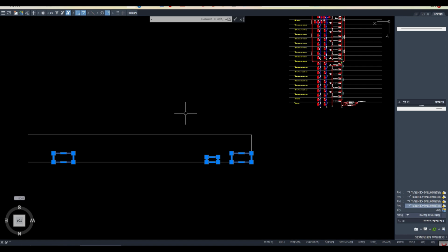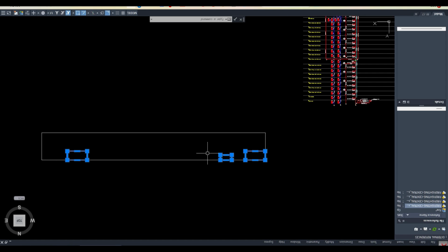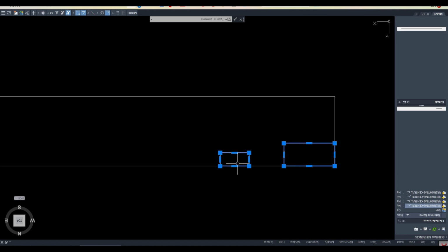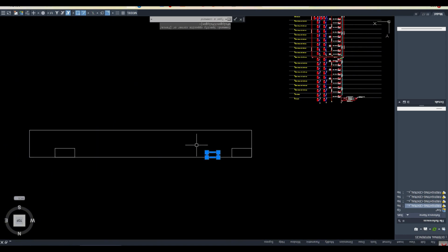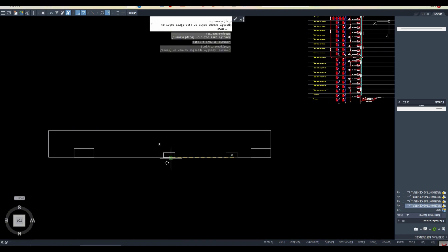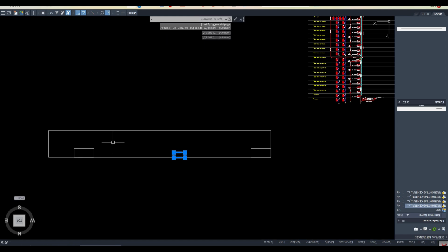Okay, so now what we were learning is this length. This is how you can decide whether the hose reel cabinets my modelers are placing are correct. Suppose to cover this board 30 meter, he is placing here, is it correct? In the mid of this corridor he is placing, is it correct? No, sir, it's wrong because our firefighting system must be close to the staircase. Correct. So it must be within the 6 meter range from the staircase, right?